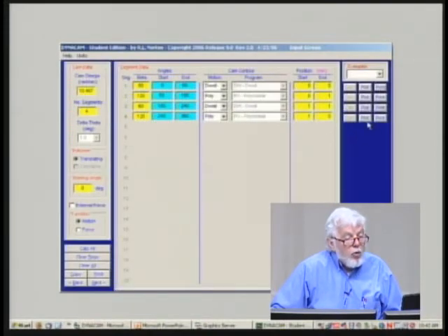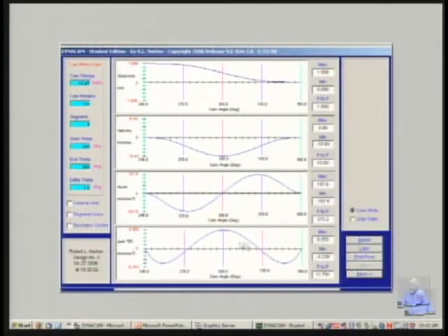Now I'm back at the SVAJ screen, and I can plot the function I just created, and here you can see the differences very clearly, neglecting the fact that this is a fall rather than a rise, which we asked for, which of course makes the velocity negative. Just look at the shapes. Velocity looks a little bit like it did before, but it's very flat at the ends here, and the reason it's flat is we told the acceleration to be 0, and we also told the jerk to be 0 there. And when I pin those down, this jerk is the slope of the acceleration, correct? If I tell the slope to be 0, then the slope is 0 here.